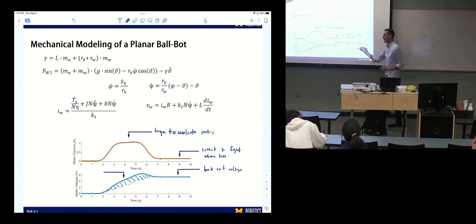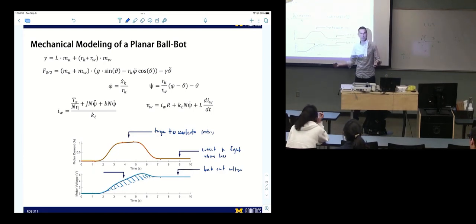The reason it doesn't look like a straight ramp, which would be almost entirely back EMF, is that we see an increase there, and that increase looks like it's connected to the current. That's the I times R term. So we're seeing the increase in the voltage required because we have a drop across I times R, which comes from a high current going through it. When the current comes back down, we see that come back down too.